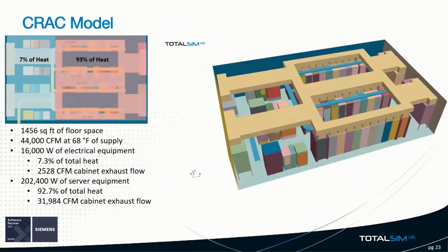The last iteration in this optimization sequence, we looked at a completely different cooling system. Instead of overhead split units, we have installed computer room air conditioning or HVAC units. An air duct was installed to connect the chimneys from the server cabinets to the returns of the HVAC unit. All heat load setup remained the same.